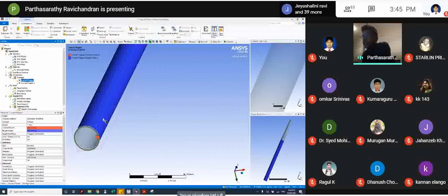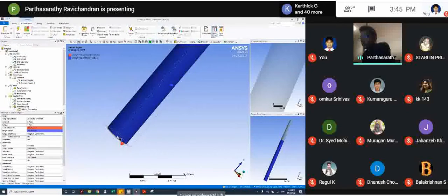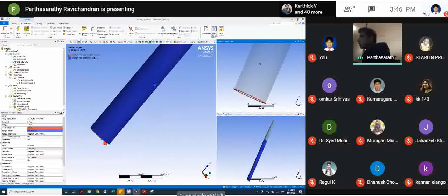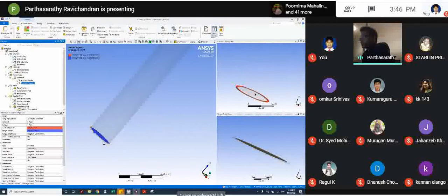One is the contact between this surface and the surface on this. So here you would be able to see that definition, that the contact of the target body to the shell surface. Now, whether that is correct or incorrect is what you have to define. If this body's surface is touching close to that, then it will try and detect that this is the actual contact surface. And the next is this top surface trying to touch the edge of the shell.